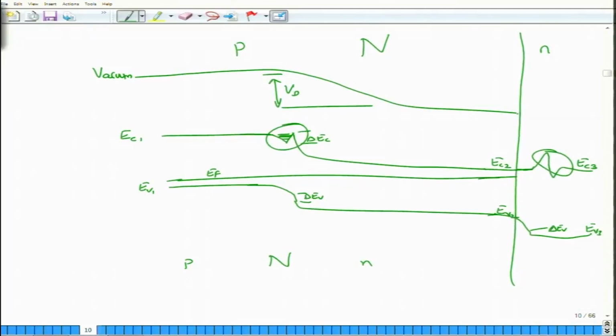So, you will have three different materials. One of the materials will happen to be having a larger band gap than the other materials. The other two materials will be of the same type, and the overall effect is that the energy levels are actually changing and the middle layer has to act like an accumulation layer. So, clearly I cannot put a small n on this side, I should have put something else on the other side, right.